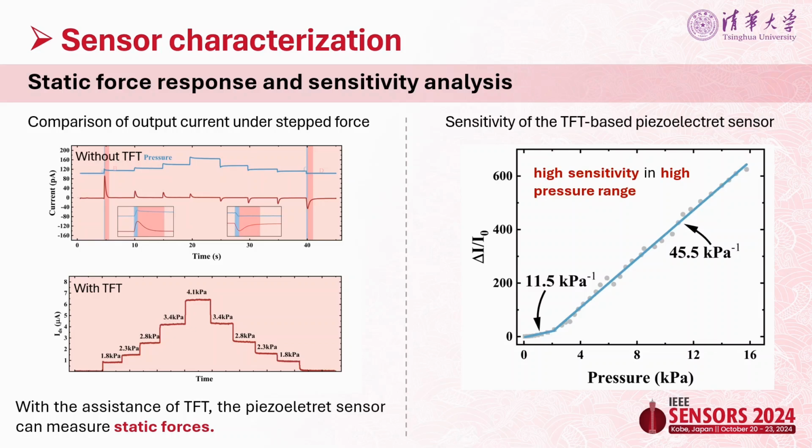And we also test its sensitivity. As shown in the right picture, it exhibits high sensitivity in higher pressure range. This phenomenon is different from conventional pressure sensors with softer materials. This result is mainly contributed by the amplification characteristics of the TFT.